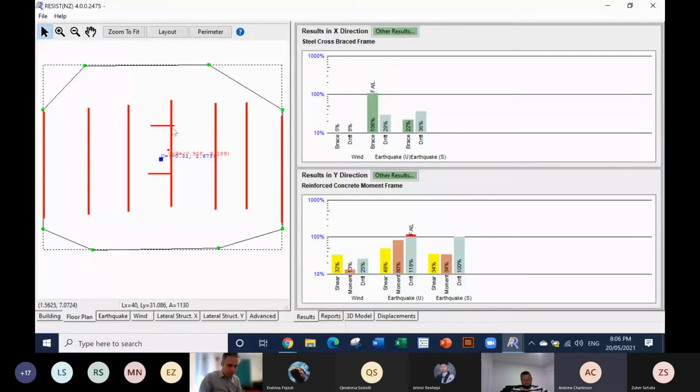Now, because these brace frames are strong in the X direction, the frames can go anywhere in plan, pretty much, as long as they're not too close. But now I've moved them closer together, the brace is failing. If I reinstate them to the perimeter of the building, then basically the design is sound once again. It's failing just ever so slightly, so I need to go back and just increase the size of the brace a fraction, say 0.37.